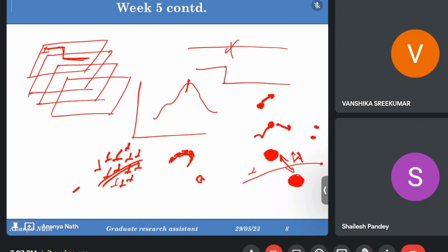So cross slip, what happens is, if there are a lot of planes like this one, and each plane is separated by another plane distance, and if this plane is having some kind of pile up of the dislocation, this plane is having some slip direction, the another plane is also having some slip direction, and you can see all these planes are similar. The coordinates of all these planes are the same because they are parallel to each other. And if all the planes are having the same slip direction, slip plane or slip system, then this piled up dislocation will try to move forward.